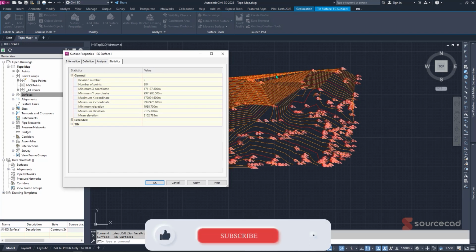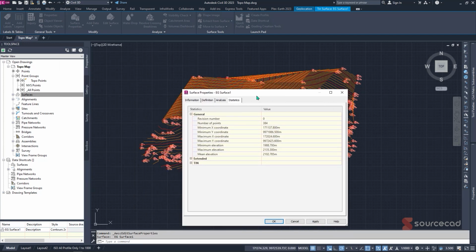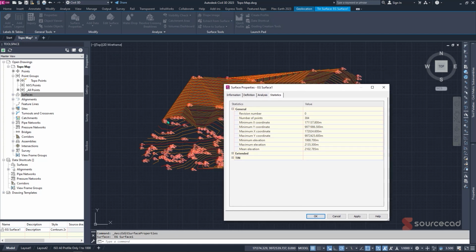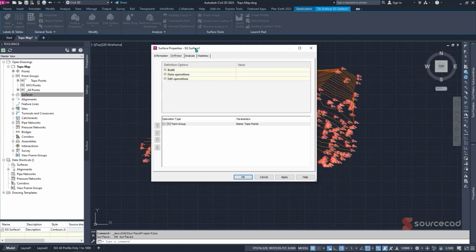But when you're creating surfaces in Civil 3D, you need to communicate to it so that it understands how to propagate the surface, because right now it is just connecting different points and triangulating different areas without knowing which points to omit and which ones to consider. And to give it that information, you go to definition, you go to building, and under this you can exclude points which are less than a certain area. So for this case, it's considering -1 kilometer or -1,000 meters.